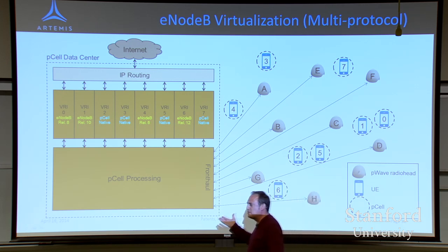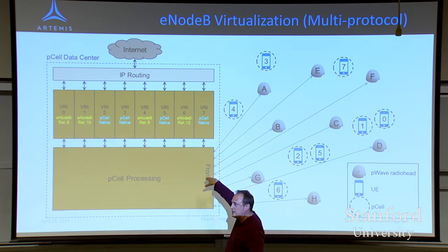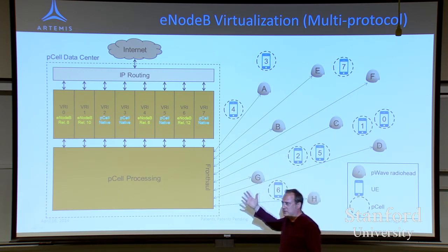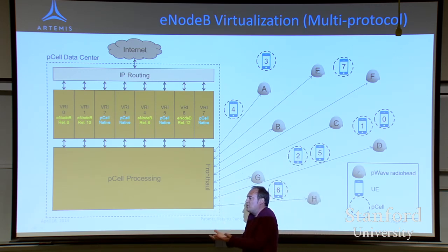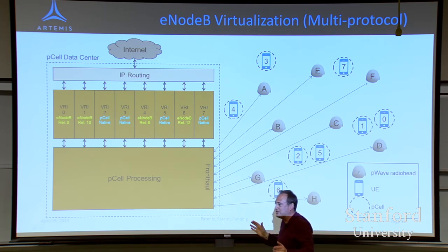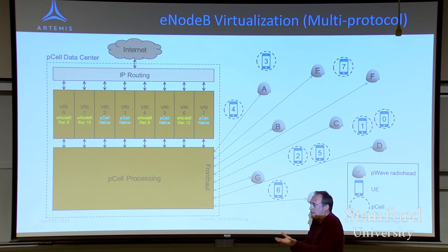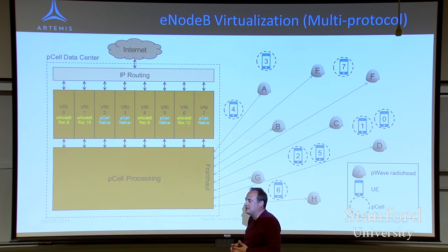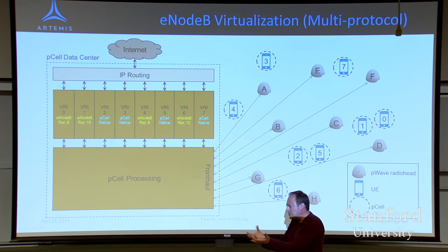I think it's about 200 or something for what an eNodeB can support. Because everybody's getting their own eNodeB, we have no upper limit in terms of the number of users. You can just keep adding VRIs. So it won't go dead on you. You won't have a situation where you can't even connect. It'll connect you. Whether your device feels it's being starved at some point or not is of course how the device is designed. And different devices we've tested actually have different starvation behavior, okay?